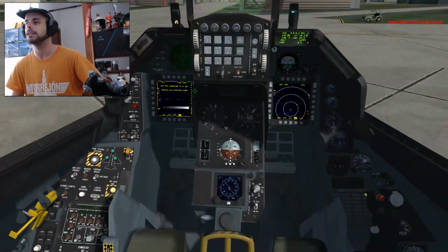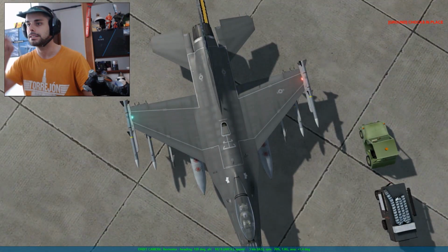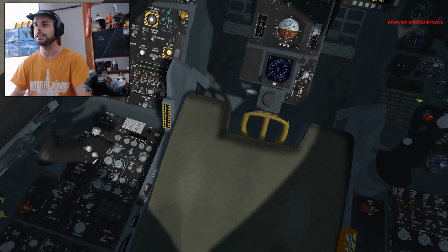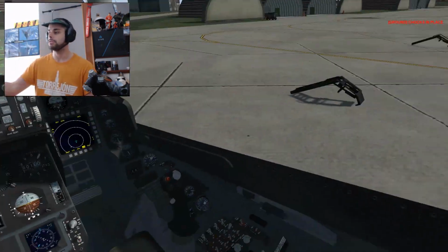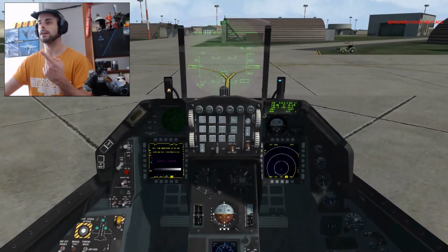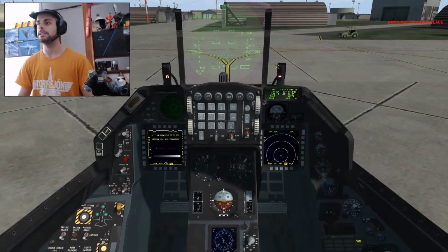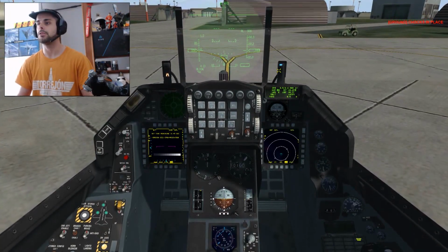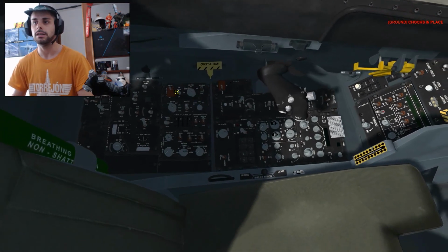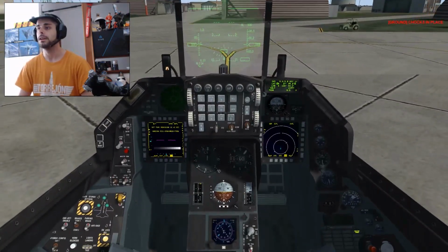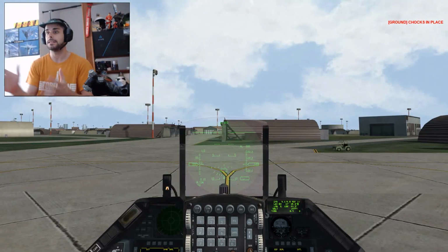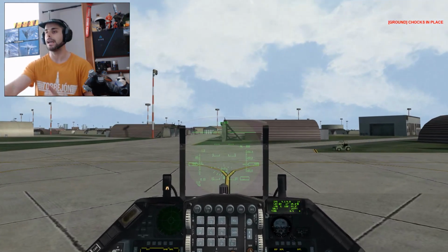Open the door. This door that is in here, as you can see in the middle. This one. Okay. Now, in your stick, push nose wheel steering on off, and you can see the light is checking the system. Okay, it's good. Perfect. Now you can close it. System is good.